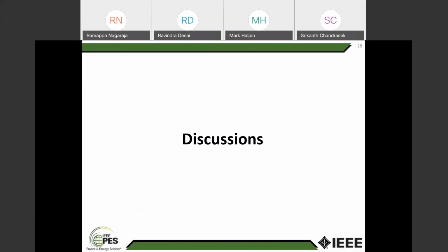Therefore, what is very important to understand here is that harmonic measurement can be done for the existing system, but the simulation studies are very important whenever you want to do the harmonic analysis for a proposed system where the injected values of the harmonic currents are available from the manufacturer equipment data sheet. Then you can always do the harmonic power flow studies, harmonic simulation studies to find out how the various distortions are going to look, and then you'll be able to take proper mitigative measures.